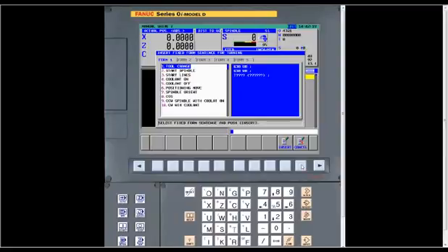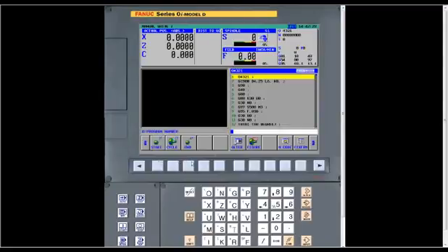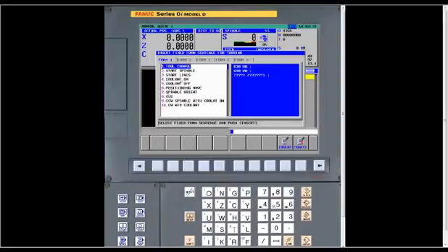different fixed forms. And just to let you know, Form 1 and Form 5, they will always be the ones that when you go into start or end, that's what Form 1 and number 5 are. Form 1 will be the start ones. Form 5 will be the end. And what you do, you just go in and set them up. As you can see, I've got tool change, start spindle, start lines, tooling on, whatever you want to put there. You just set it up however you want.